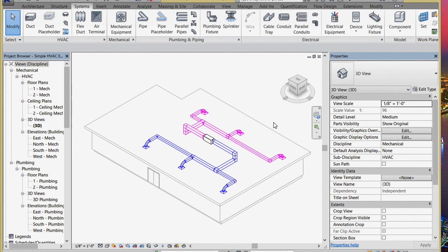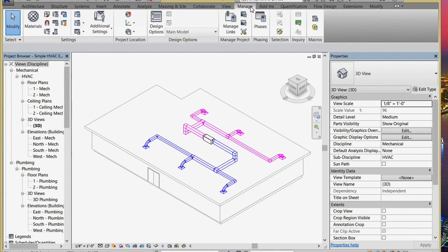The whole notion of heating and cooling really starts with where we started at the beginning of this quarter. It's the project location. Based on that project location, there's a temperature profile. And based on that temperature profile versus the temperature we'd like to maintain in the different spaces, we're going to heat or cool the space to try and maintain that. That's going to be affected very radically by the surface materials and the thermal properties of those things. So it all starts, under the Manage tab, if you want to go there, with just choosing the project location.